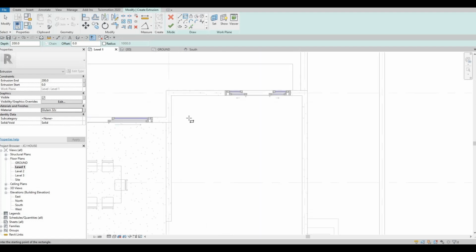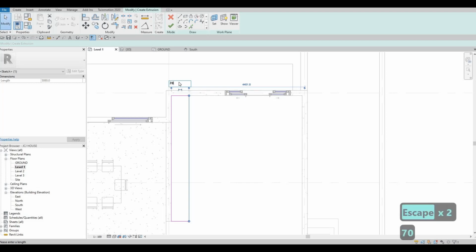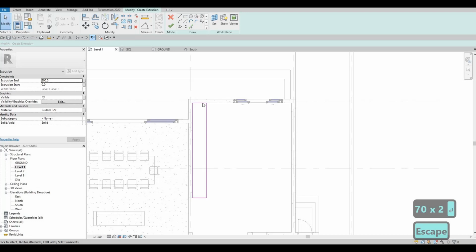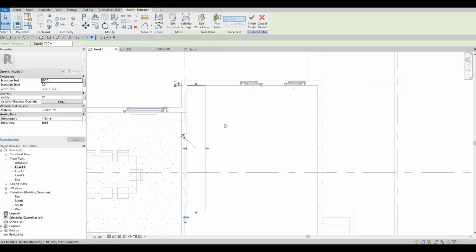And then let's add in our base. I'm going to maximize the space right here, and then I'm going to make this one 700. So that's our base, and then from here we could click on Finish, and then we could set the extrusion to 900.